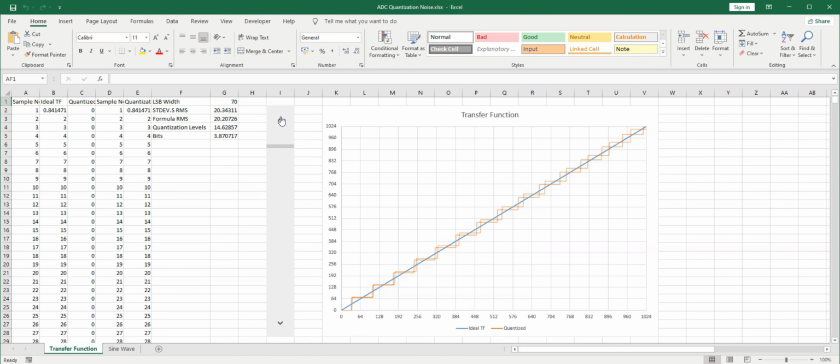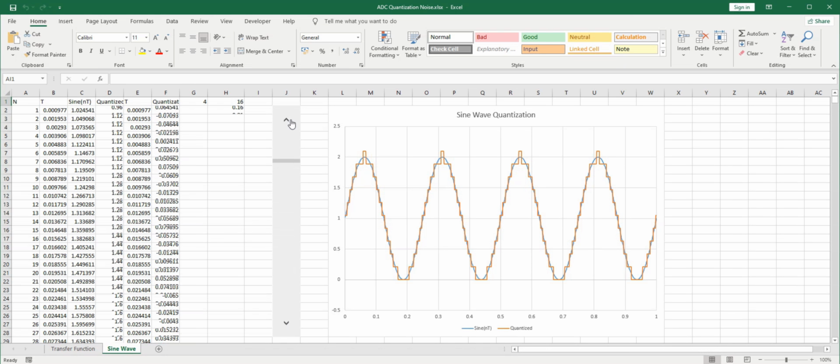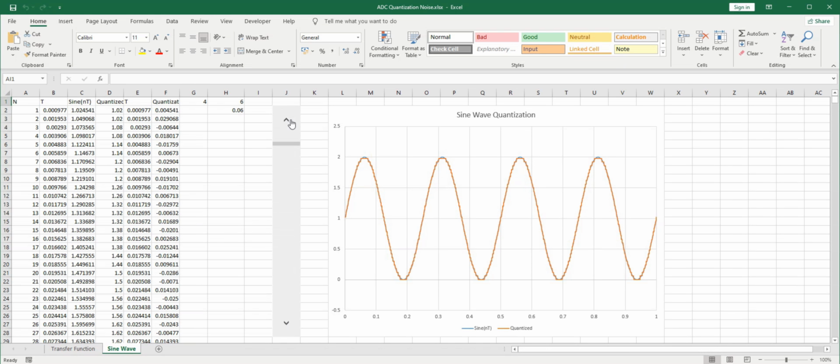inherent conversion process. Signals in the real world have basically infinite resolution, which the ADC reads and rounds off to the nearest value from a set of values, determined by its resolution. For example, an 8-bit ADC converts a voltage within its input range to one of 256 values. Compared to the smooth input signal, the digitized signal is much blockier.